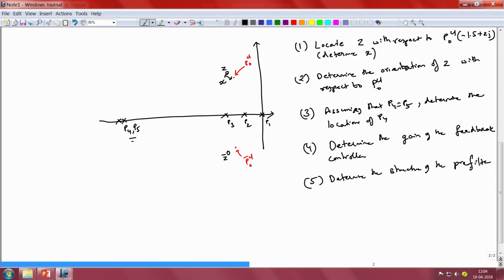So there is one pole whose location is uncertain. So when this uncertain pole's position changes, in what particular manner does the closed loop pole's position vary? This is something that needs to be determined, and this is something that is specific to the particular parameter that is varying. So we have to undertake this design step in detail once again, and we cannot borrow this from our discussion in the previous clip.